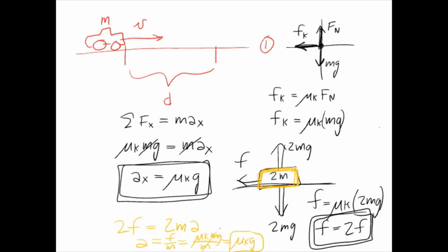Okay, they all have the same speed limit, because the bigger thing that affects the stopping distance more than anything is the coefficient of friction. The thing that affects your stopping distance more than anything, as far as the conditions of the car, is the tires. Okay, it's the gripping coefficient between the tires and the road. If you have better tires, you're going to have a better deceleration rate and a better stopping rate. Also, obviously having the anti-lock brakes, as we discussed, makes a big difference. But the mass of the vehicle doesn't really make a difference, because if we double the weight of the vehicle, we double the friction, but we need twice the friction to stop something that's twice as massive in the same distance. So the stopping distance actually stays the same.